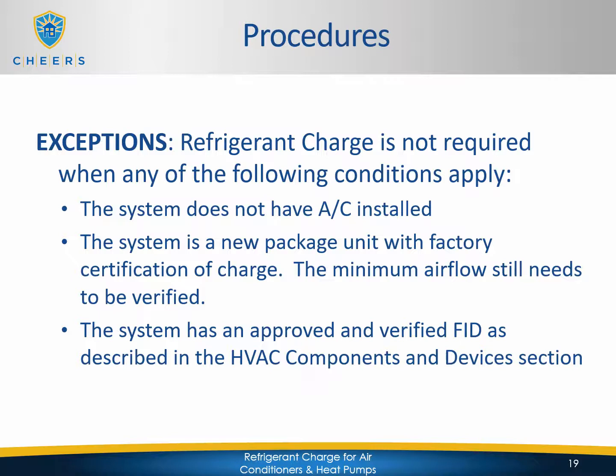The next one is if the system is a new package unit and it has been factory charged, so it will be certified to be properly charged from the factory, and this will be indicated in the documents. So the installing contractor will need to provide the make and model and AHRI certification number.